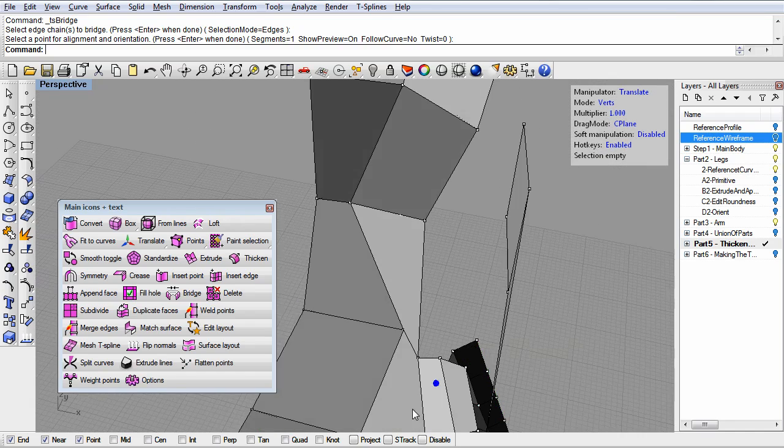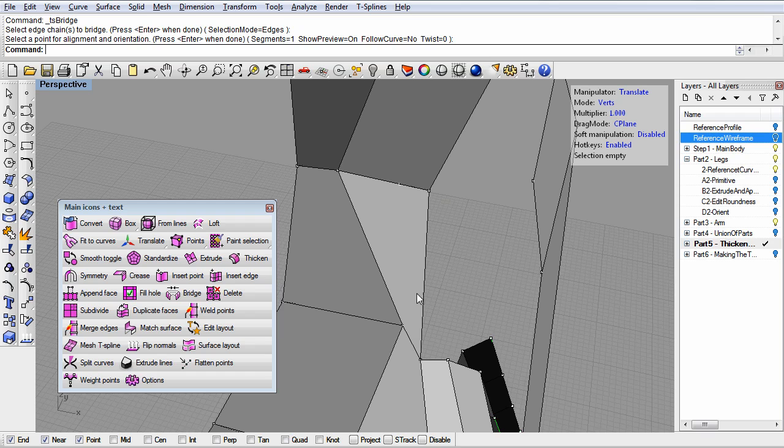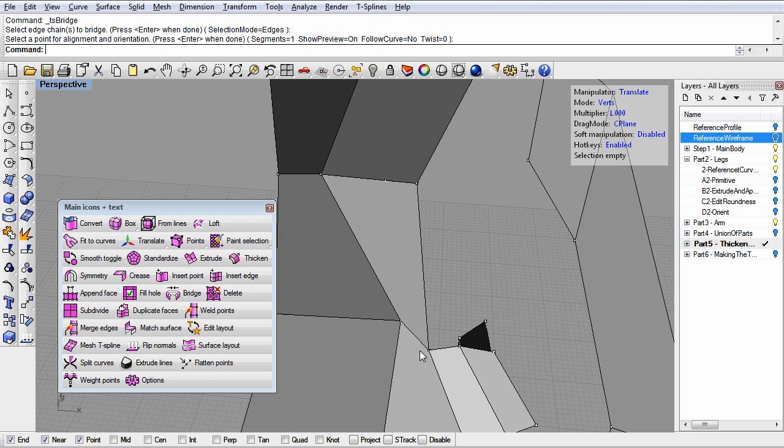So one other thing to note is that my surface back is kind of coming up and it's kind of pinching this off, and it would be great to kind of unweld this and open it up, so it can flow both down the leg as well as here to the main part of the chair. So if I want to unweld this, what I can do is select this edge, and I can right click on the merge edges command so I can unweld that edge.